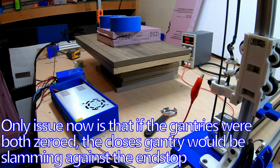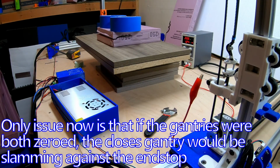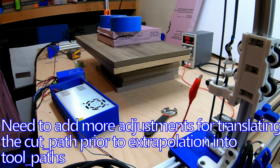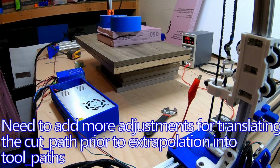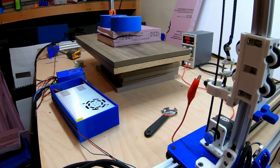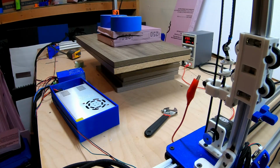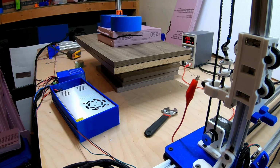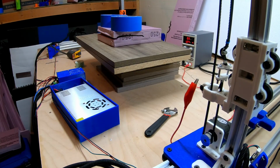Now the one thing I didn't end up constraining is that, say if the trailing edge forms a line that goes past that, I don't currently adjust for that, and that's what you see here. When I align the leading edge with the actual wire 0, it ended up sweeping the trailing edge to the point where one of the gantries ends up needing to go backwards. And this could cause issues if you had the machine zeroed. It would end up just pounding against the end stop.